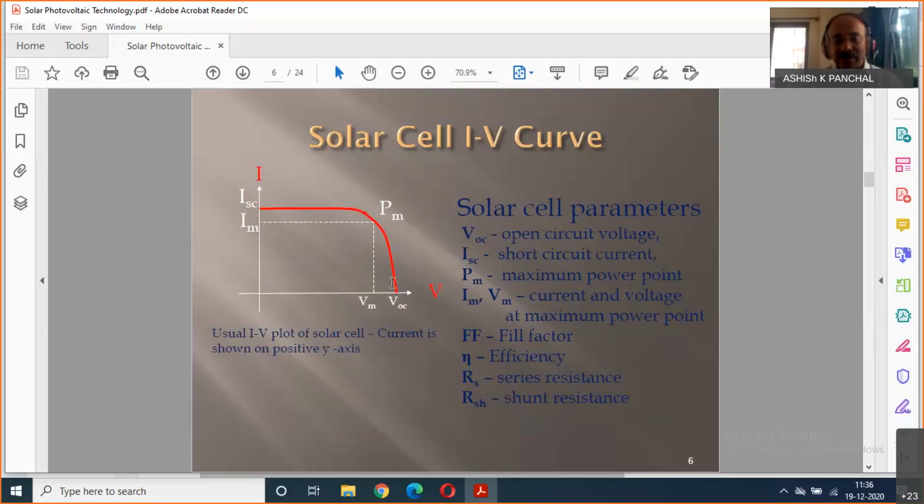Okay, now let us connect 1000 ohm. So what will happen? With 1000 ohm current is almost zero, and then we connect 10,000 ohm. So this circuit is as good as open circuit. Okay, no current will flow and the voltage is open circuit voltage. So this way I have measured the IV characteristic, right?